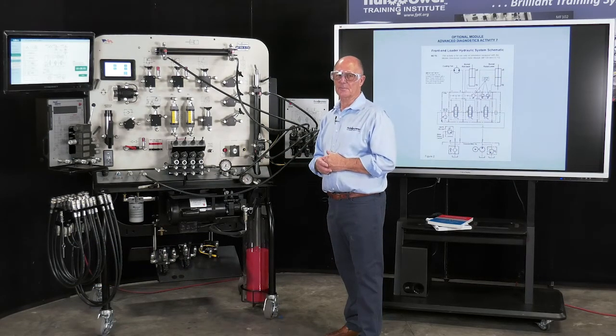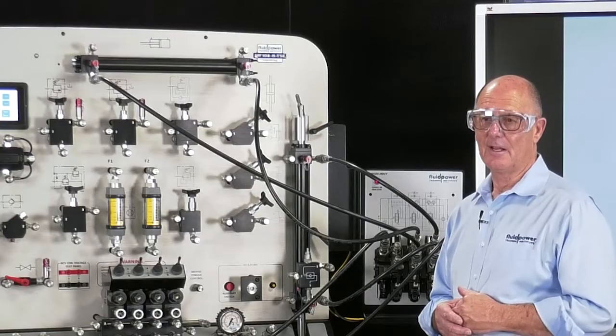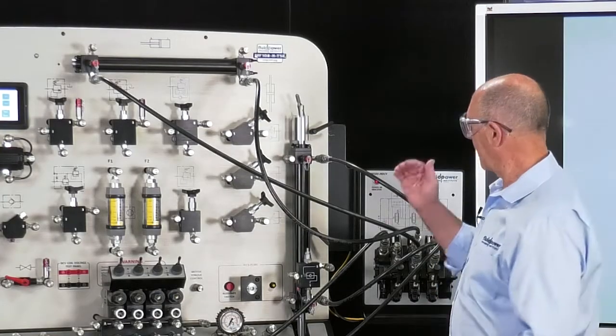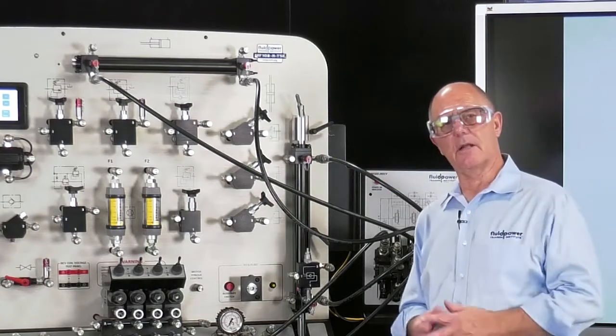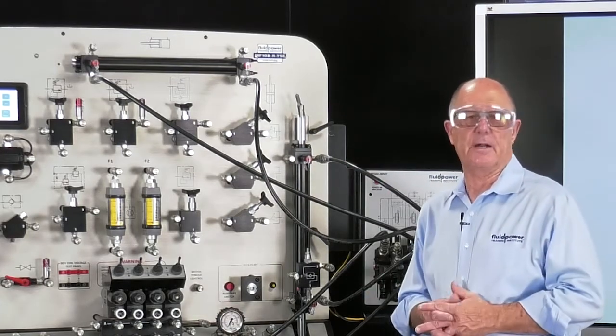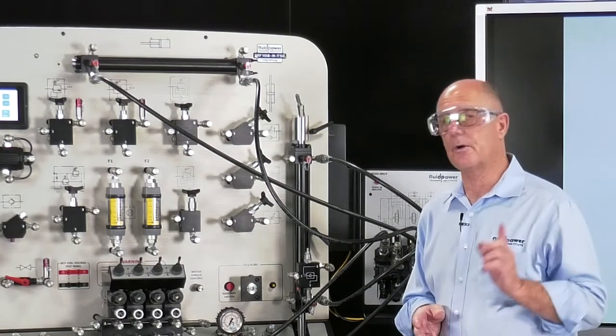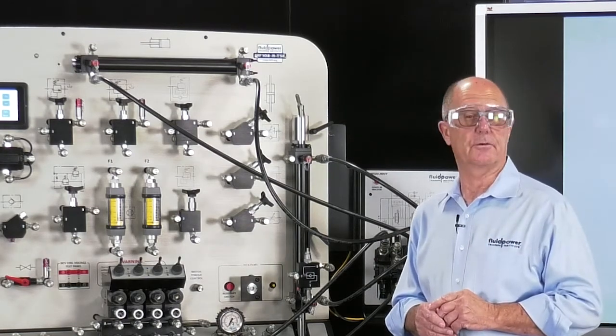That's why you test in the opposite direction to which you're drifting. If you've got two seals and you're drifting down and you test in the top port, you're going to go to the seal that might not have anything wrong with it, and it's going to tell you everything's fine. It's a false positive. So you always test in the opposite direction to which you're drifting.